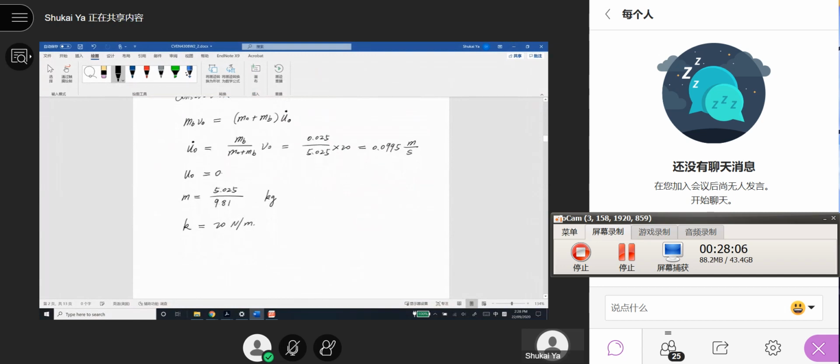And for sure, the final expression for this vibration should be equal to, let's check omega n. So this should be equal to u0 cosine omega n t plus u0 dot divided by omega n sine omega n t.